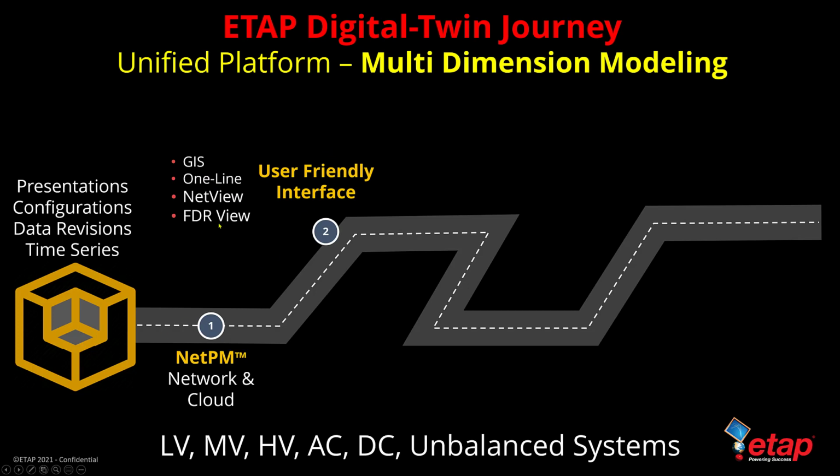Again, this is where multiple engineers can work together to either enrich this model or perform analysis on it. The analysis is performed using various different visualizations of the electrical information, which could be through geospatial data, schematics like a one-line diagram, net views, which is a simplified substation connectivity view, or feeder views, where you're just looking at a single breaker or a single feeder that leaves the substation.